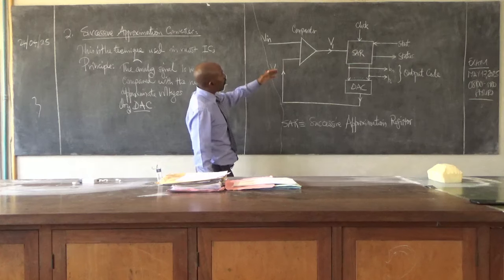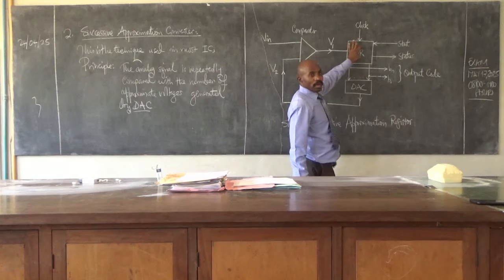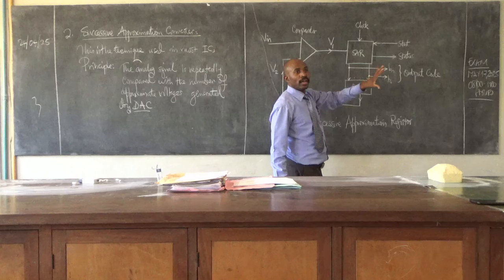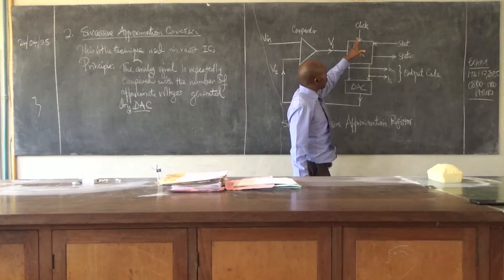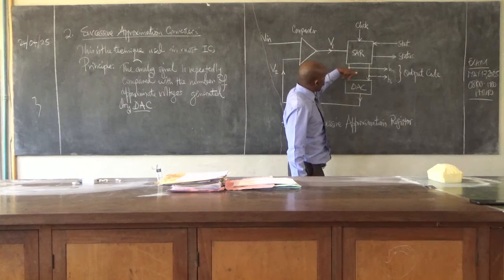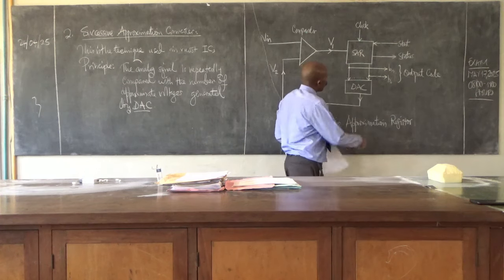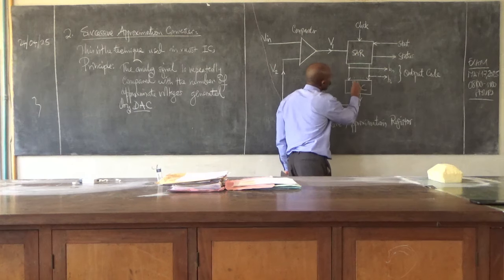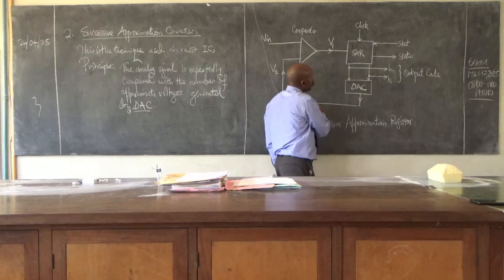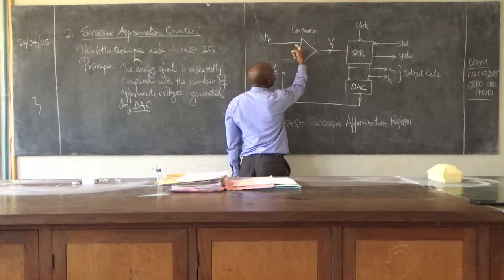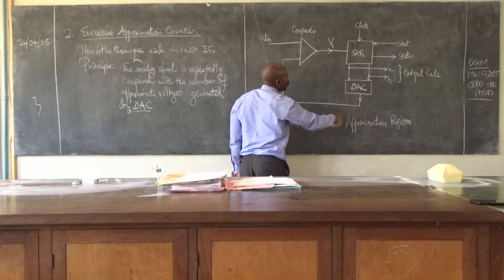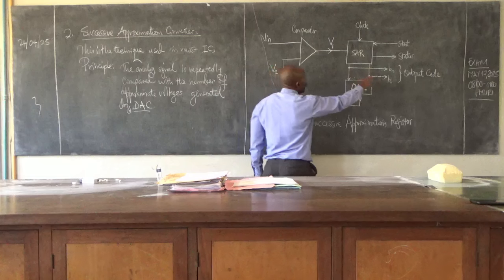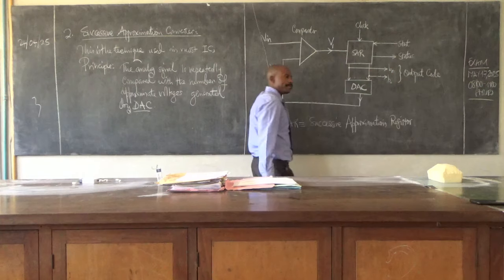So this is our register, which successively corresponds with the clock. So when you start, it produces the signals, and then this signal gets converted. We use a converter. It converts this signal, gives us a voltage V2, which we keep comparing with Vn, and then we get V1. And the process keeps coming on as we produce these bits.